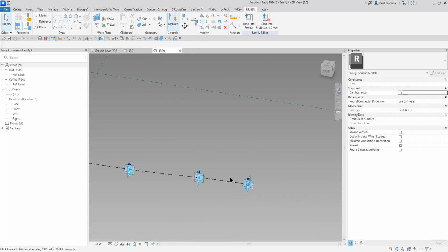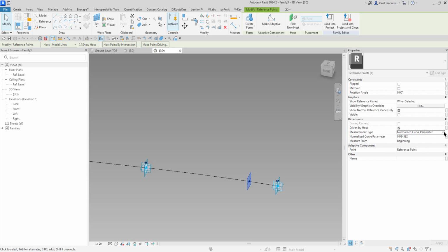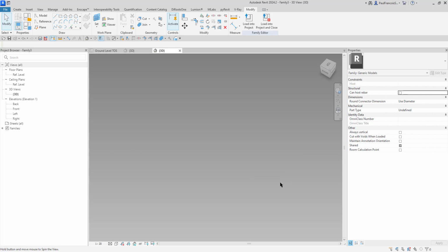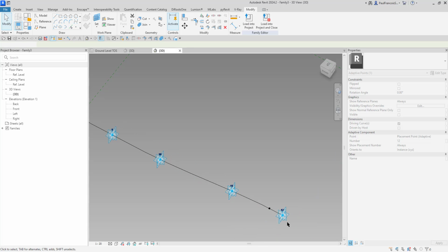We do the same thing at this end over here. We place a point, we hover over the line, it's going to select the line, we pick on the line, we select that point, we change that point into being defined as per a segment length from the end, and it's going to be 120 millimeters from the end. All right, so again, if we move part of the line, then the point on the line is going to move along with it. If it becomes longer, it's always going to stay a certain distance away from that line, as you can see over there. So that's quite powerful.